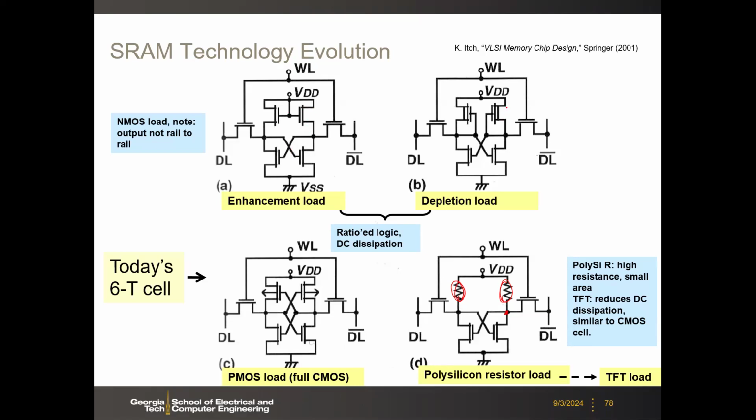And of course, you can have the NMOS between the depletion mode and the enhancement mode, which means the VTH of the NMOS could be negative. Then you can use that as a node. But again, those are ratio logic. It's not like rail to rail. And you also always have the large leakage path from the VDD to ground. So that's why today the 6 transistor SRAM cell becomes the mainstream, like CMOS logic becomes the mainstream.